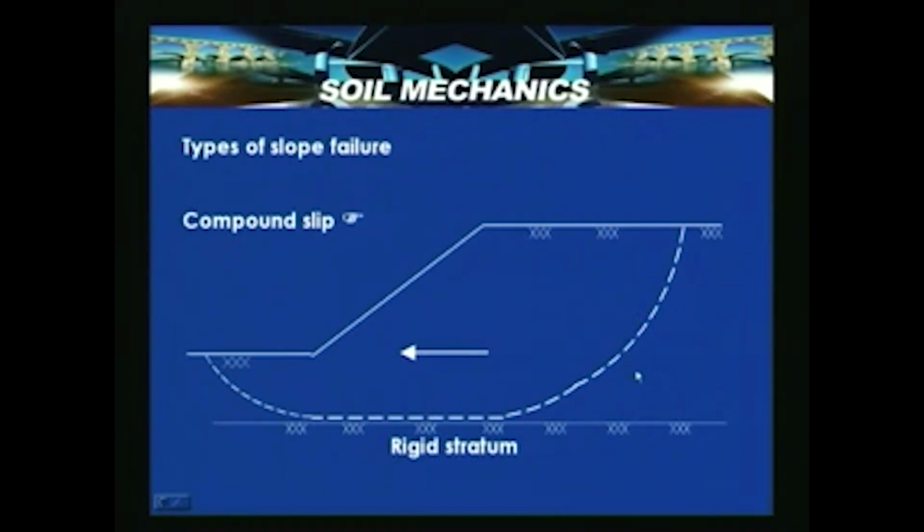That means if you take a sample from here, this is the possible failure plane which the soil can experience under stresses. Here the soil will be subjected to tension, or extension. In this case, this particular interaction almost resembles the way it works in the direct shear test.